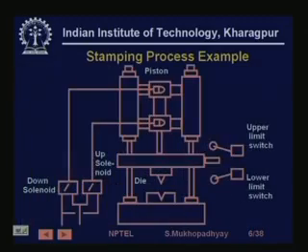So we come back to our old stamping process example which we have seen in earlier lectures. So here is a stamping process, we know this process, so we have made some addition to its functionality to be able to explain certain features of a system and make it more complete. So the basic principle is the same, that there is a piston and there are two solenoids, a hydraulically driven piston which goes up and down and makes stampings. Okay, so if we now try to write its list of actions, try to create a linguistic description of the process operation, it will look something like this.